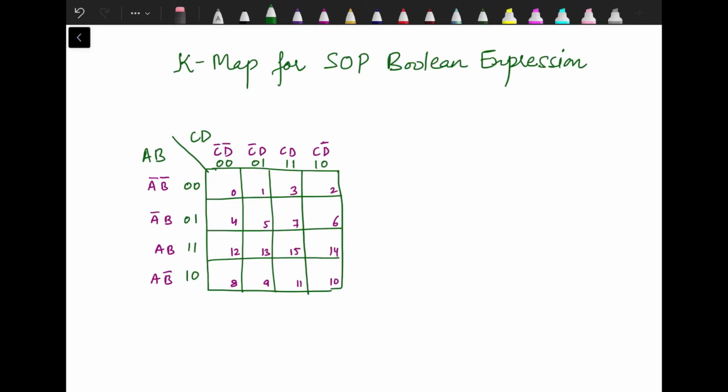In that video, I had discussed the K-maps. We have seen how we can make the K-map for a 2 variable, 3 variable or 4 variable problem. In K-maps, we have the cells corresponding to each combination of the input, and these cells are labeled using the gray code since we need that there should be only a variation in one of the variables when we are moving from one cell to another cell.